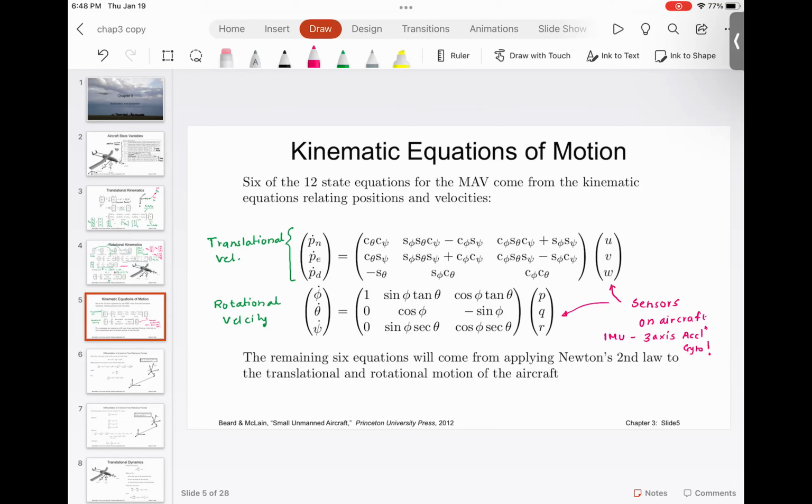Now, you get the P, Q, and R for the upcoming time step. So you use the previous roll, pitch, and yaw values to compute the rotation matrix. You get these new values of P, Q, R, use the previously computed rotation matrix, and get phi dot, theta dot, and psi dot. You understood this approach? So this is sort of a recursive approach of numerical integration. And this approach works because your time steps are very small. So you are integrating these equations at 1000 hertz.